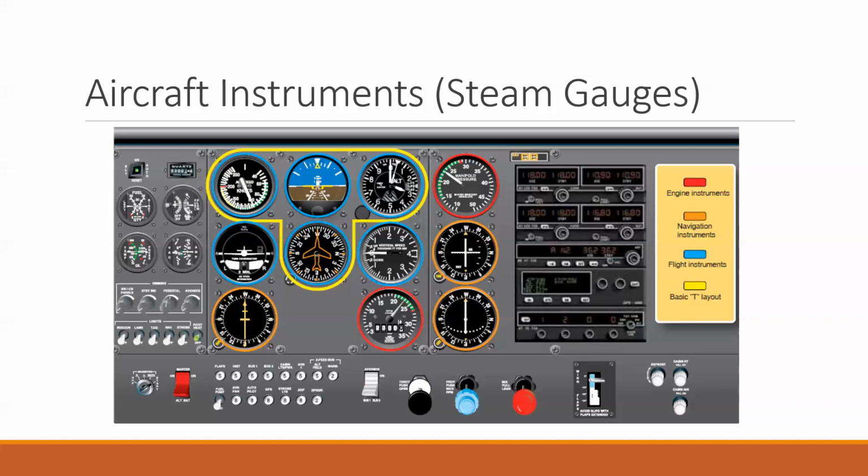So pretty simple. This also does adjust for the pressure of the air, and so that's also connected to a little port on the side of the aircraft that measures what we call the static pressure of the air, and it calculates that into the equation as well. It's a pretty simple device, just has some springs and gears and some other stuff in there.